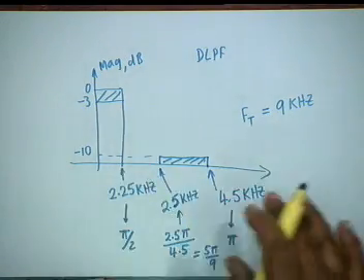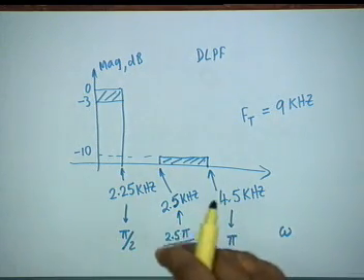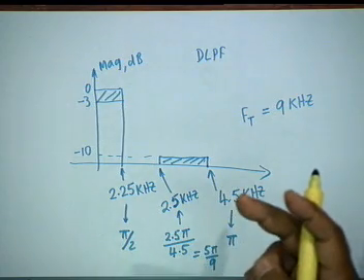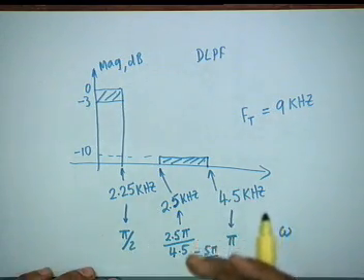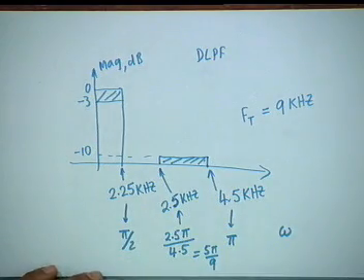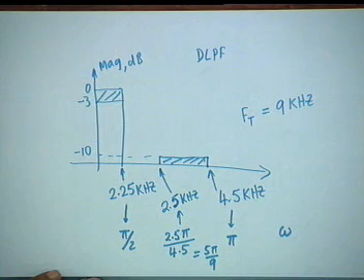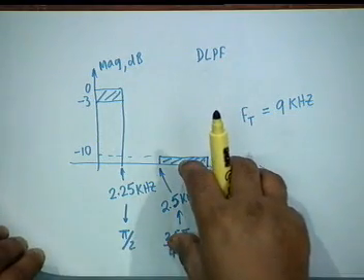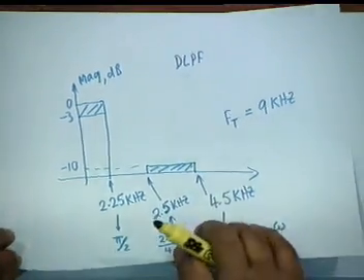By the usual procedure, we find out the normalized analog filter, then we make the analog normalized filter into a digital low pass filter using the bilinear transformation, and get a transfer function which satisfies these specs as the following.